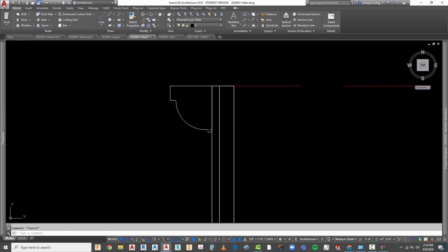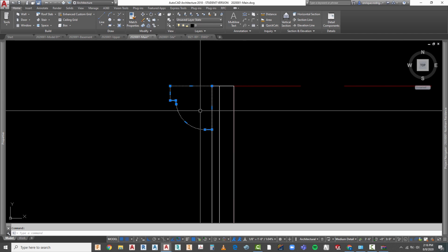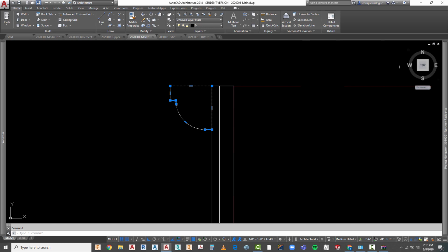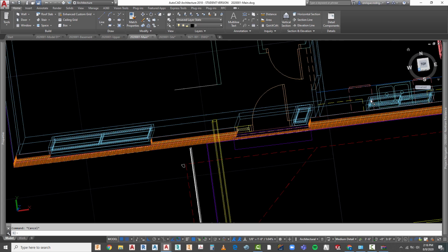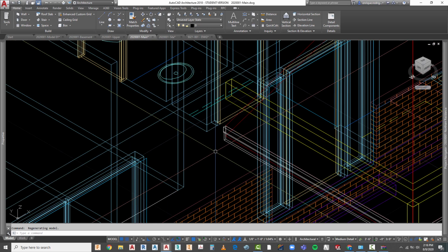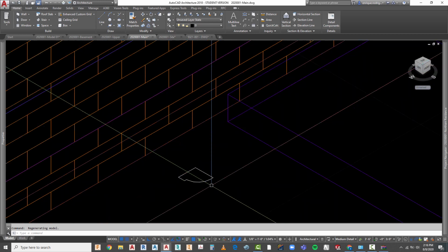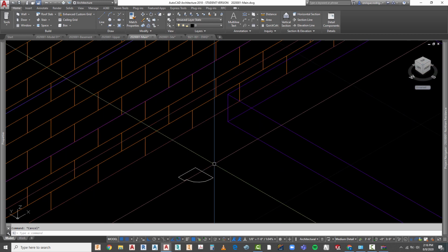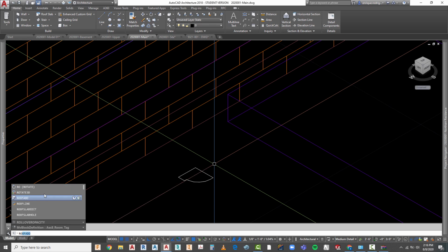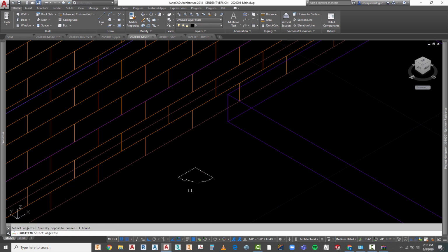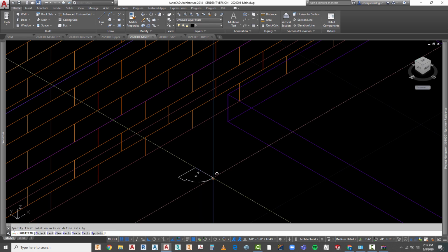So let's go ahead, and in order to make sure that our edges are going to be solid, if you notice this was drawn down at the bottom, I'm going to rotate 3D using the same command. Rotate 3D, select it. Just going to select the end point here.